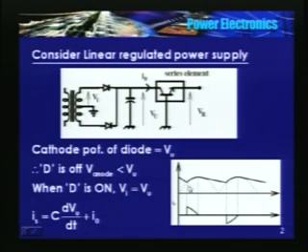So if you observe the source current waveform on the oscilloscope, there is a very high peak current here. A high current starts flowing here; I am neglecting the inductance. If there is no inductance, a large current will flow and it slowly dies down. At this point the current becomes 0. So there is a sharp pulse of current here, and after pi, through the negative of this diode, a sharp pulse of current for a very short duration.